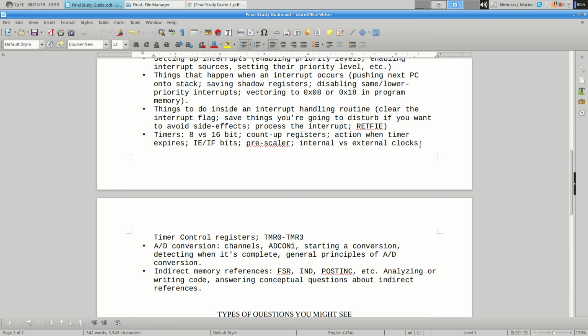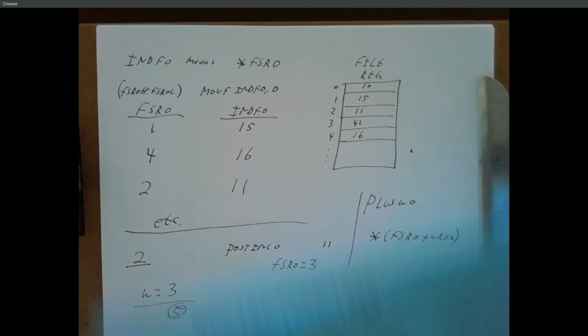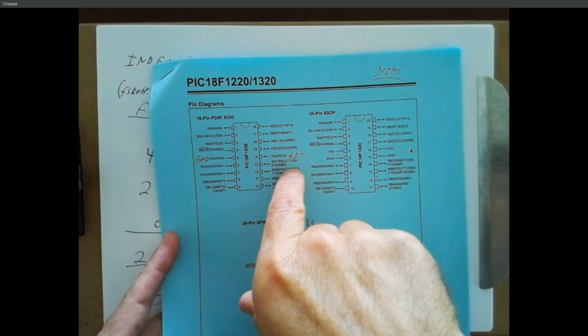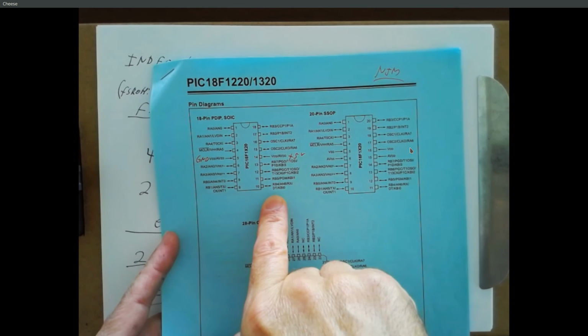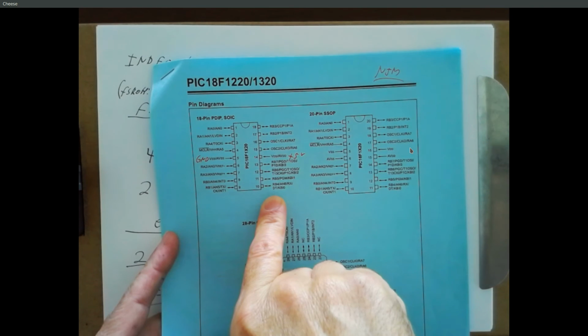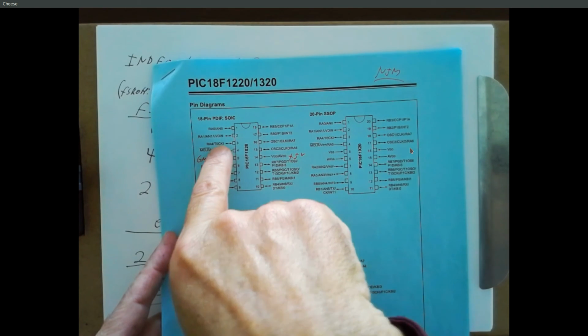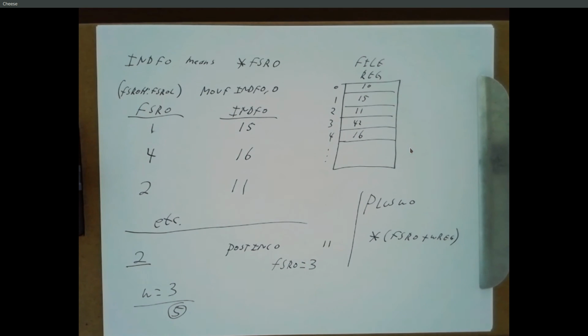And we've always used the internal clock, but we can drive these things with external clocks also. There's pins you can pick on here. I believe oscillator 1 and oscillator 2, but there could be other ones. Maybe T0 clock in, that you can use to say, hey, instead of using the instruction cycles as the source of my clock, I want to feed in something from the outside. And now I take a 555 and have it generate a pulse every second, and now, same thing, but instead of an 8,000th of a second, it's 1 second. And every second your timer register increments and so on.